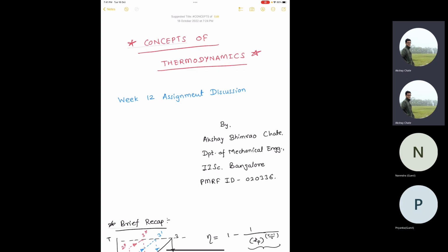See, if you ask me, it should be the heat rejected to the ambient divided by the ambient temperature. In the first two terms you are taking the system things into account, only this is the entropy change in the surroundings because of this whole heat rejection process you are considering in the end. And if you are saying this Q value is correct and the ambient temperature is 293, then this 1.6277 is wrong. It should be 1.7697 something.